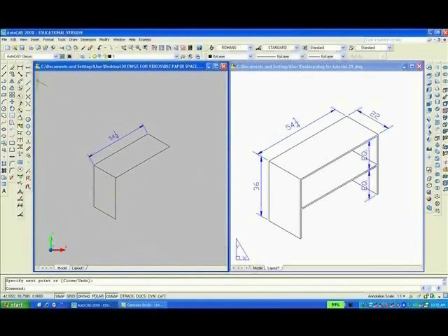Also, you can draw a line from that corner down, 36, enter. Hit the F5 key and bring it over there, enter, or escape. And I'd want to break, BR, enter. I want to break this line.